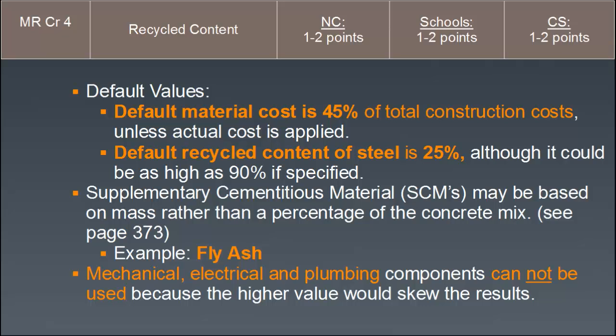The difficult part is getting the steel industry to actually report those percentages and not give you general statements such as steel is 100% recyclable. That type of letter from the manufacturer will not work. You need to get the actual percentage based on weight of that scrap post-consumer recycled content that's melted down into that batch that goes into your building. So it is project specific.